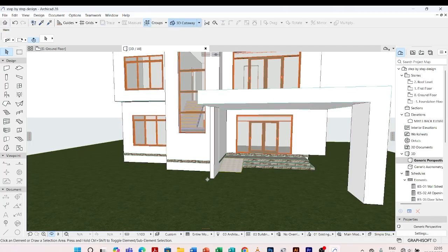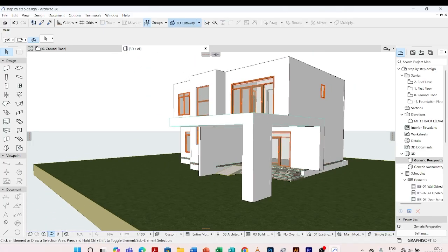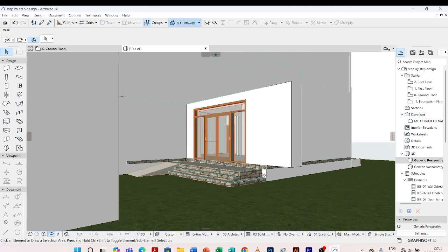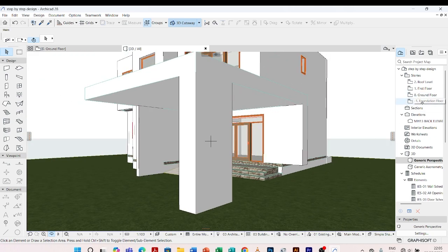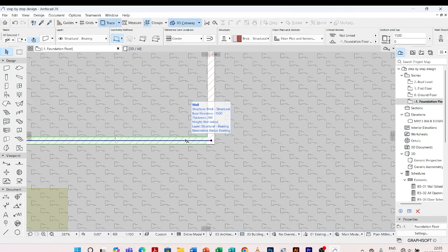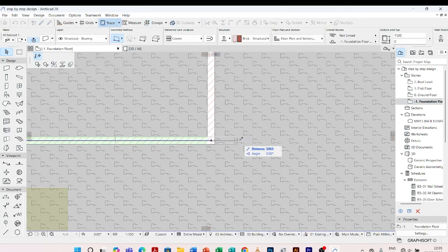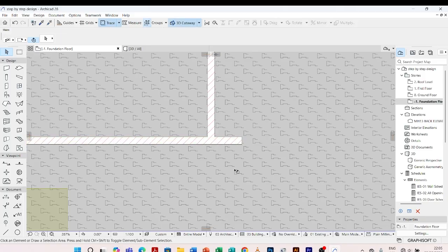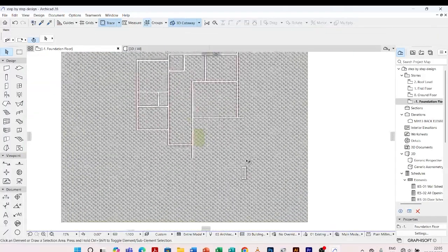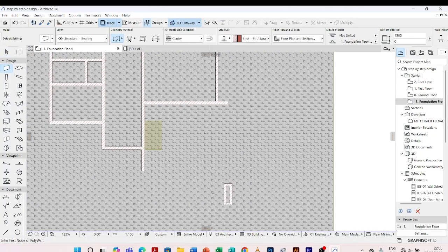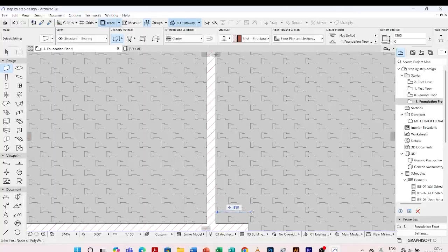After that, the same way, we shall need to drop down or create foundation for this wall we had created here. So I'll come to my foundation level. I can simply extend this wall. It is in the foundation. Click it there. Then I'll draw these walls of 150 millimeters. I'll come and pick parameter of this. I draw here.